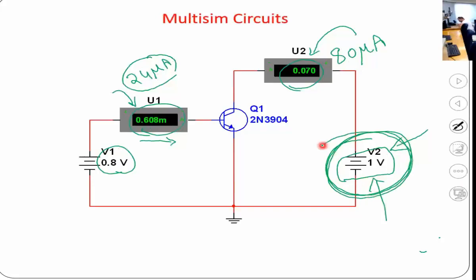It's like that same faucet example with the water. If the faucet is completely off, that means the transistor is not on. If you increase the faucet, the tap itself, that means you are increasing the base current. That means you will have more flow of water, correct? But if the faucet is all the way up, that's the maximum you can go, right? So that's the maximum current you will get from the collector side.